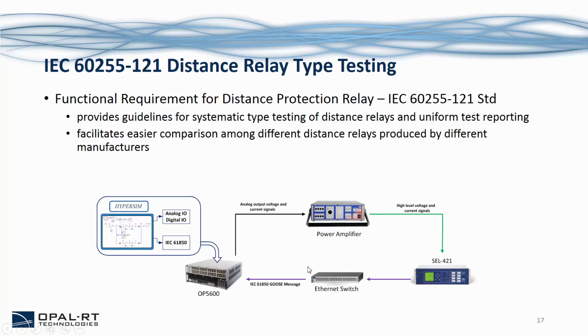The figure here shows a typical setup for a protective relay closed-loop testing. So the power system model will be simulated in HYPERSIM and running in real time on a real-time simulator. The simulator will send out analog signals through the power amplifier to the device under test.